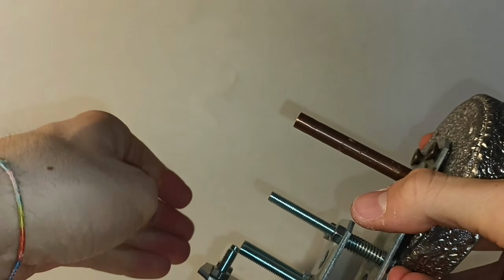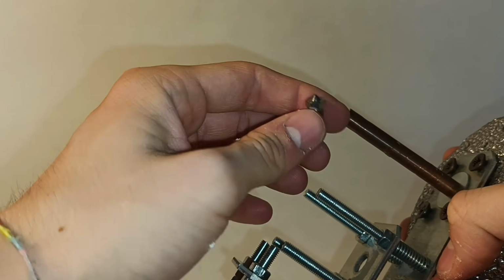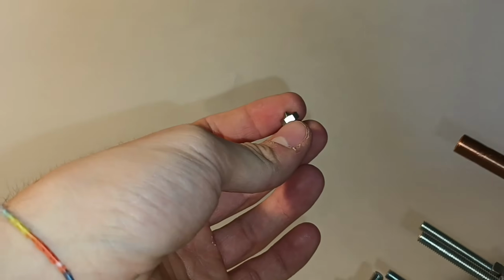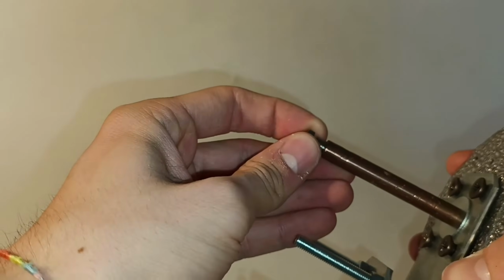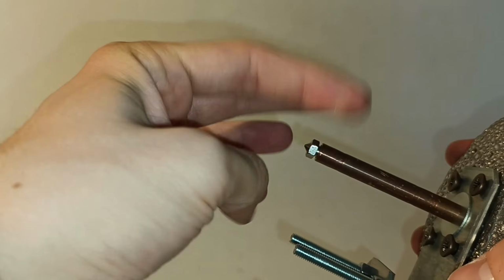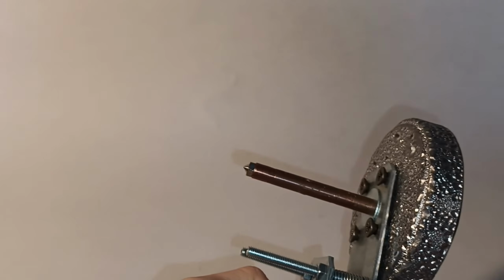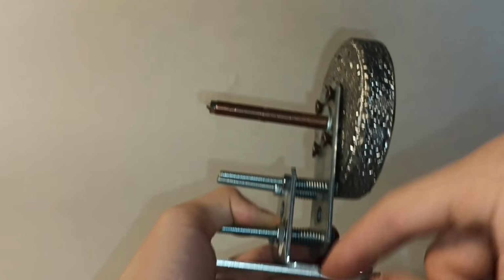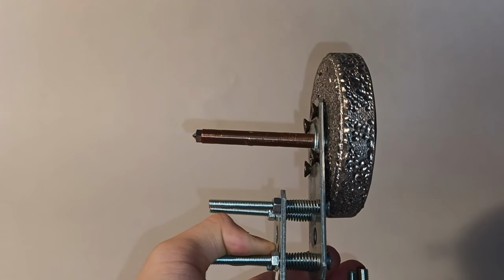And the second most important part of the collimator is the output nozzle collimator, which is the smaller diameter, because this is the one that creates the final diameter that our X-ray beam will have, and it can simply be screwed on here like that. The hardest part was to make a hole that was straight through the tube, so it runs parallel to this surface, that is parallel to the other surface here, and so it doesn't block the X-rays.